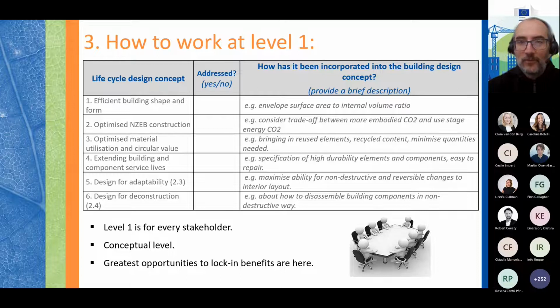So this is fundamental. Whether it's a detached house, a semi-detached house, a terraced house, or a block of flats, this makes a huge difference to how many materials you need for a given internal floor area. It also affects the ratio of internal volume to exterior area of the building envelope, and this in turn affects the potential heat gain and heat loss across those envelopes, and also the quantity of insulation that might be needed, and so on. So something so simple as the shape and form of the building can have a massive impact on life cycle carbon.